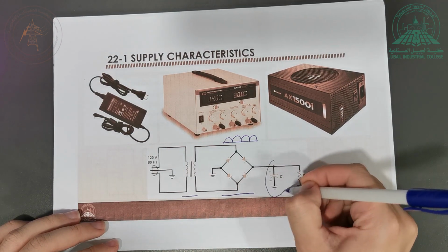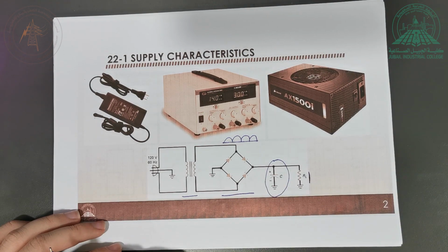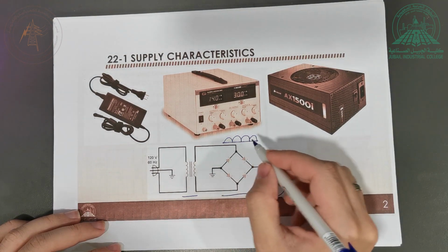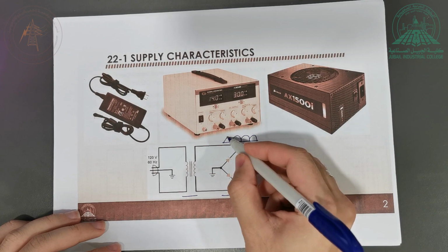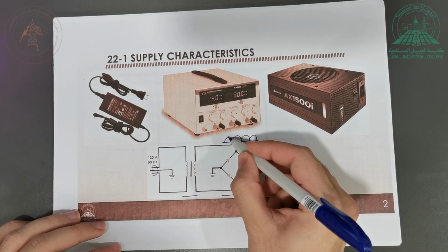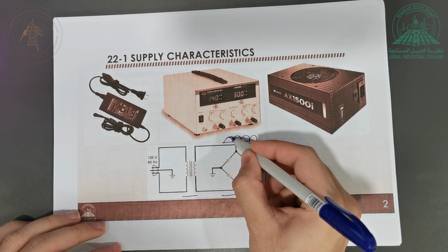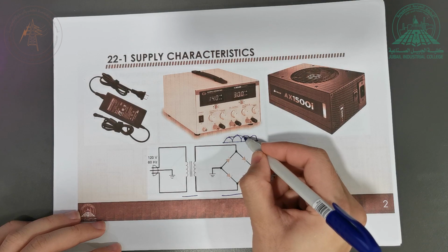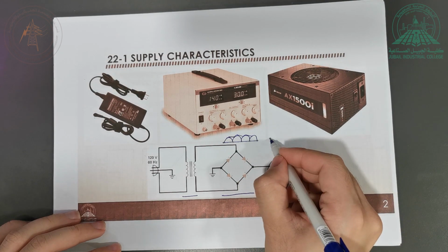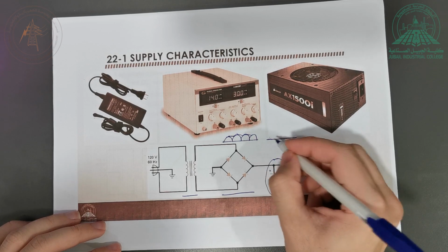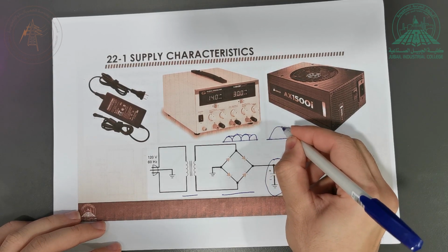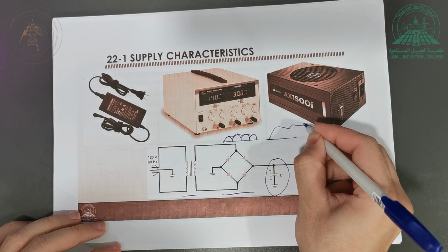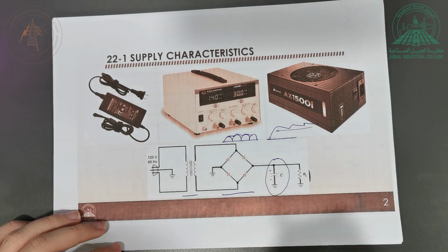After that, we have this capacitor, which acts as a filter. The job of this capacitor is to charge with the signal, and then when it reaches the peak and the signal goes down, the capacitor will discharge from its own charge voltage, such that the voltage is not going to drop suddenly, and the signal will look like that, right? And then it's going to charge again, then discharge, charge, discharge. So the resultant signal at this point will look like that. It will go up like this, then to be something like this, right? These are called ripples, right?